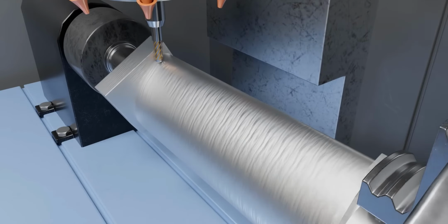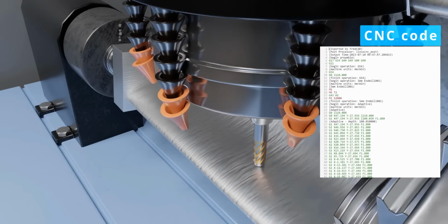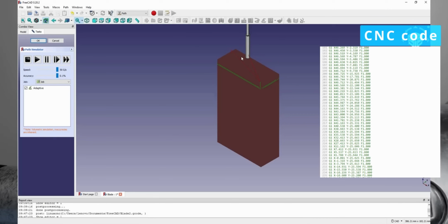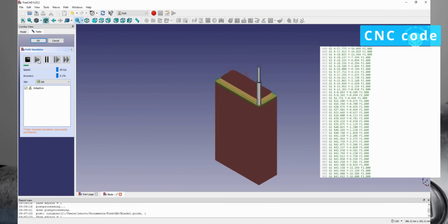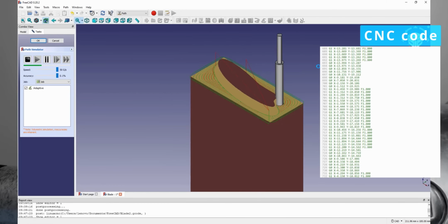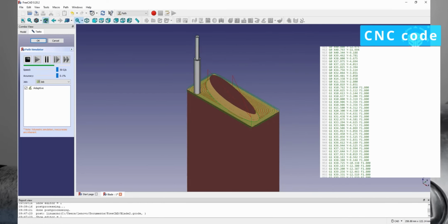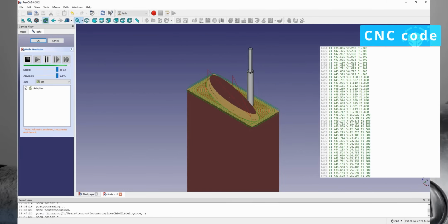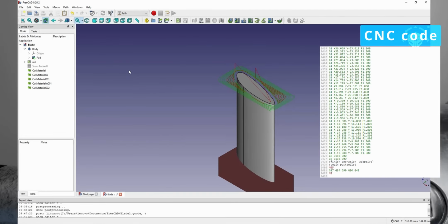As you can imagine, the CNC coding required for such a complicated shape is also complex. However, thanks to modern CAD/CAM software, this is easily achieved. Just feed the CAD shape of the blade and other machine parameters to the software, and the G and M code will automatically be generated. What's even neater is that the software can even simulate the tool path. However, if you want more accurate control over machining, you can still write this code manually. Now all you have to do is feed this code to your machine.